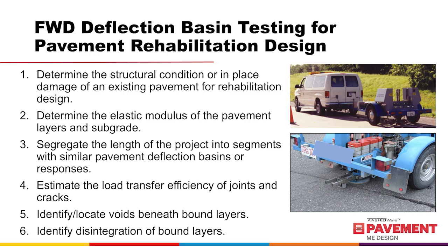The fifth area is specific to rigid pavements by estimating whether there is a loss of support or voids beneath the PCC slab. The sixth area is more specific to asphalt pavement by estimating the occurrence of disintegration, like moisture damage and other mixture deficiencies in asphalt layers.